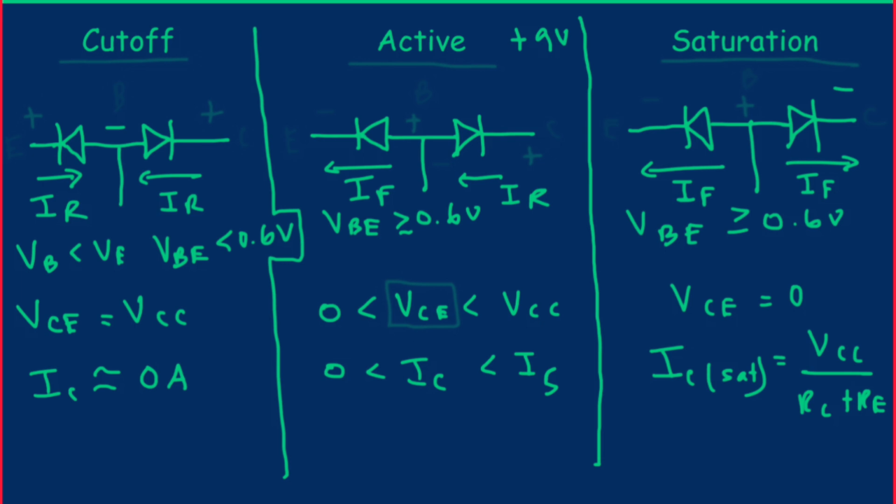From a more advanced and scientific perspective, the collector current is described by an exponential equation. IC equals IS times e to the power of VBE over VT, where IS equals reverse saturation current, and VT equals thermal voltage, approximately 26 millivolts at room temperature. This equation shows that the BJT is a nonlinear device. However, engineers often linearize its operation using biasing techniques to design stable amplifiers.